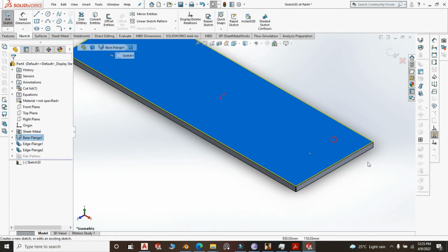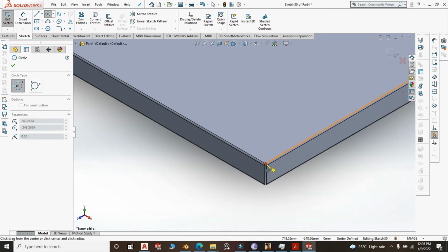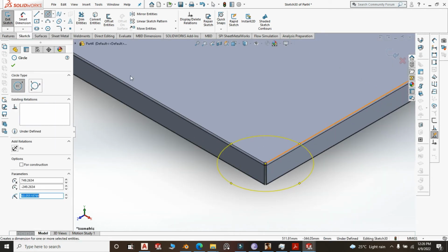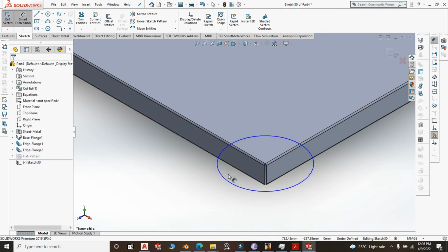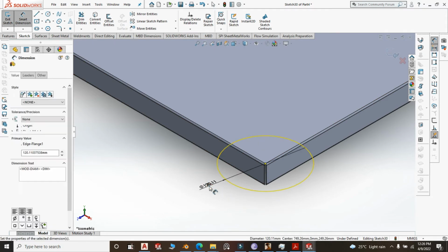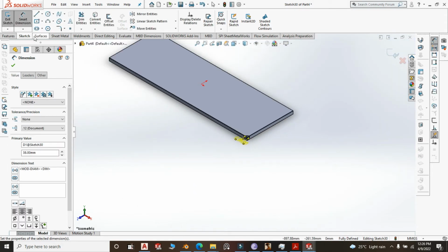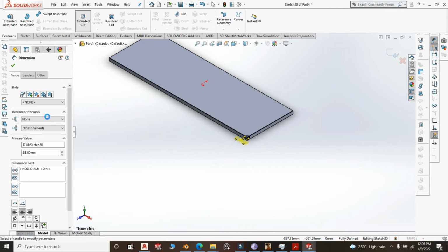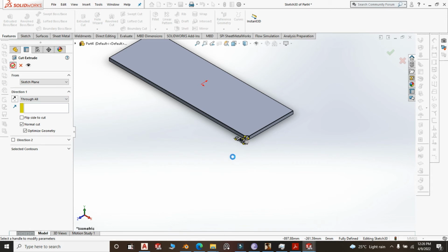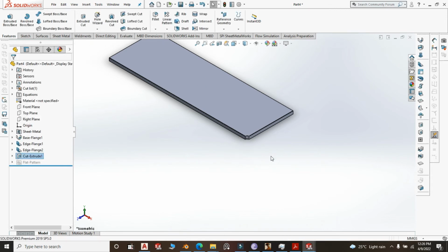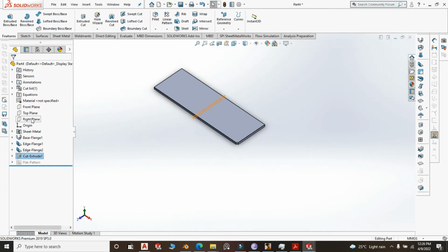Sketch, new sketch. Dial 38. We didn't exit the sketch. Choose dimension 38. Extrude and cut through all. Now see how your notch will be like. Yeah, let me just complete this rack.